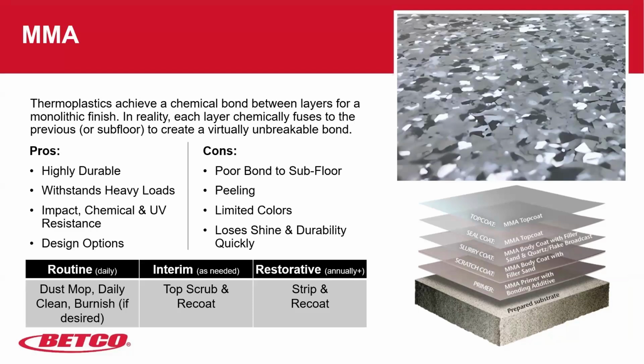One of the challenges with MMA is that it doesn't seem to want to bond to the subfloor, the concrete down below, very well. So that's when you start getting peeling up of that poured floor. And then also it seems to lose its shine and durability quickly. And that's why a correct maintenance program is very important.